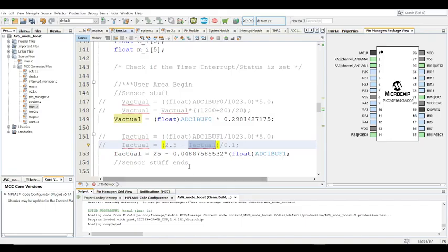Sometimes it's not 2.5. Just make sure you sense that and actually look at that with an oscilloscope. Don't use a multimeter to get this baseline value. Use an oscilloscope, because an oscilloscope will show you most likely what your microcontroller is also going to see. The accuracy of an oscilloscope is a bit compromised according to the leads you're using, but I still think it's a little bit better than using a multimeter, because the multimeter sort of just averages that value out.